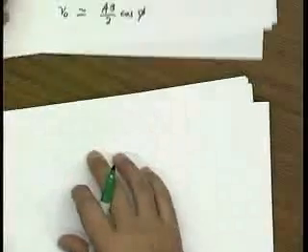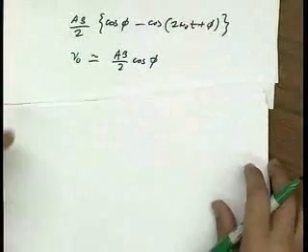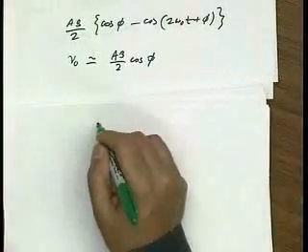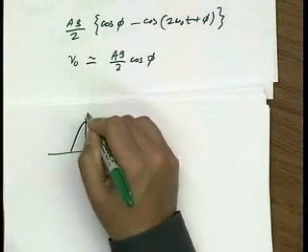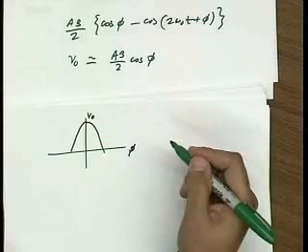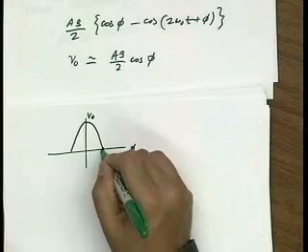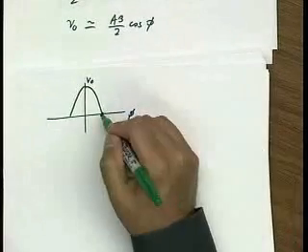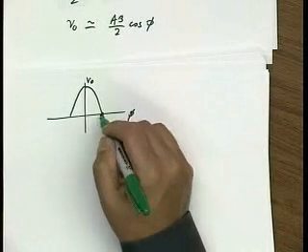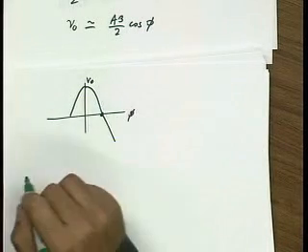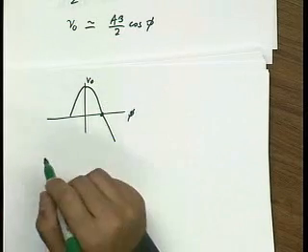So this is actually already, you can see, not a linear circuit. If I look at the V out transfer function versus phi, it looks like cosine. And you can see that if I want to maximize the gain of this circuit, the gain is maximum right around here, where cosine crosses pi over 2.